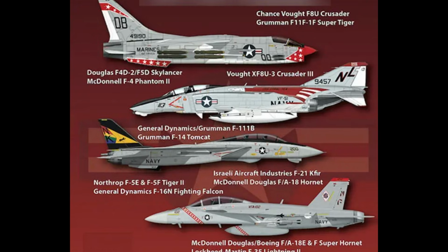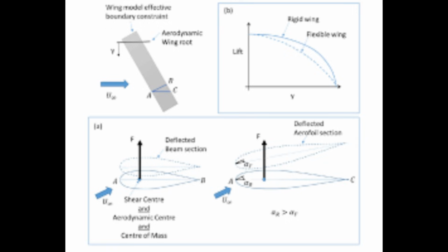Structural design had to adapt to new load paths created by sweep. Wings experienced increased bending moments and torsional loads, requiring stronger spars and refined materials. This pushed advancements in structural analysis and fatigue modelling. Aerodynamics and structures became more tightly coupled disciplines rather than parallel concerns.